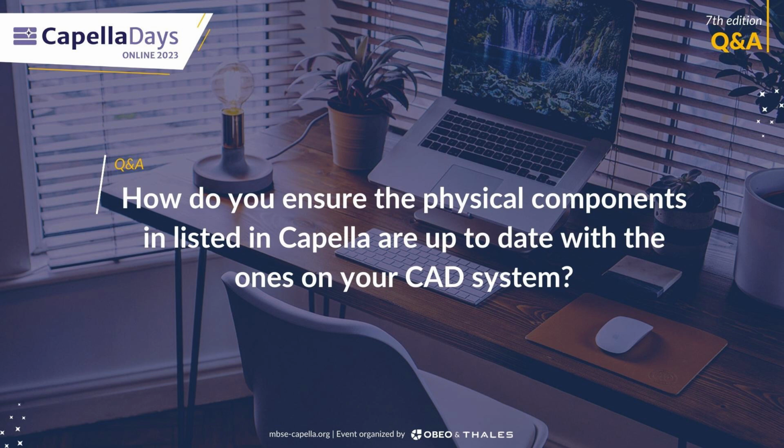The other thing we can do is, we are building traceability from MBSE to our BOM structure. So we actually have part numbers and revision information that is being fed to the MBSE model. And if we wanted to make sure that the FMECA really is up to date, that is a piece of information we could capture in the FMECA, right? Along with the part description, we could have a part number and the rev number, and then perhaps on a weekly basis or whatever, based on your project frequency, we run a check to see if your FMECA is still up to date with the latest Python export from your MBSE model, and try and match up those part numbers and rev numbers. Okay, thank you very much.